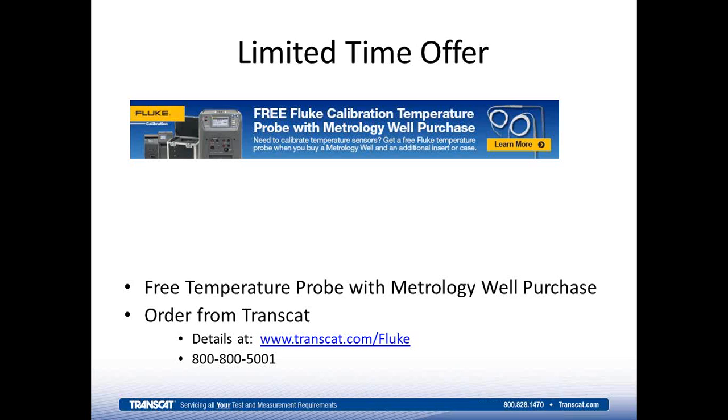Yep, good question. You can use any RTD or SPRT that you'd like to be your reference. If you remember the slide about the GUM compliant uncertainty analysis, we would have an uncertainty associated with that reference probe. So if it's an SPRT that was calibrated in fixed points, the uncertainty of the reference contribution would be quite a bit smaller than if it's an RTD that was maybe calibrated by comparison. Most of the time, the probes that we see used as references for dry block calibrators are typically just an RTD, but in some cases, a metal sheathed SPRT is used as well on some of the deeper probes. I hope that helps to answer that question, but it would be okay to use either.